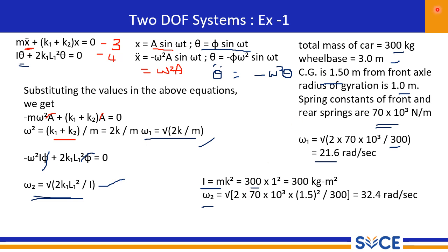It is very important to note what kind of problem we solved. It is nothing but we took a multiple masses system and multiple springs subjected to an external harmonic force. Then what will happen? The response depends upon the system parameters like masses and spring constants. So we calculated the resonance frequencies. Resonance frequency is going to be very, very important.